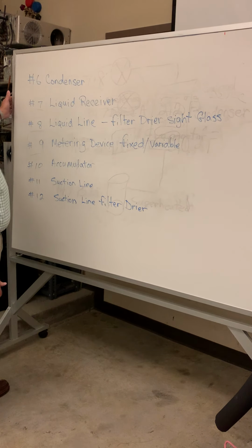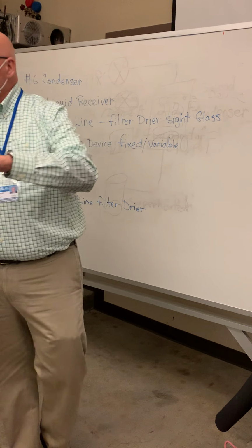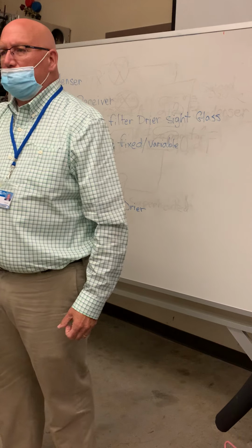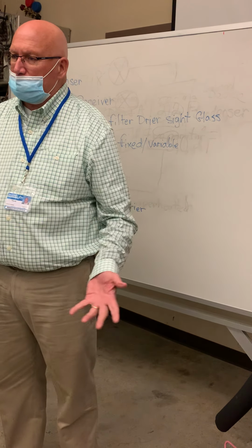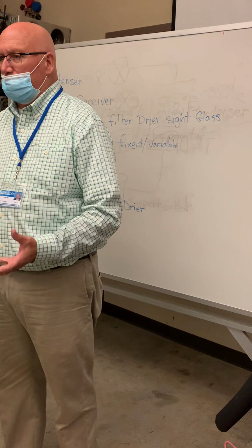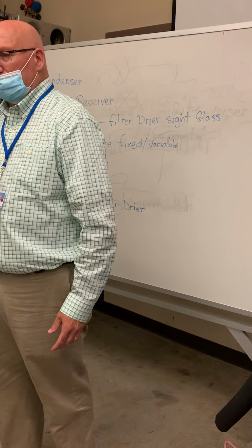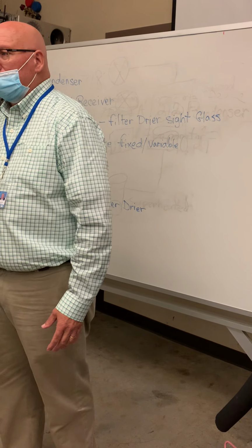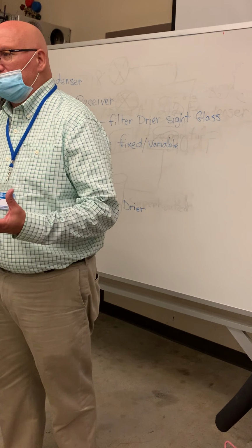What are the other pieces to the system that we're talking about? Well, condensers is one. The condenser, that's the one where I take the sponge and I squeeze it out. That's the one that says it may be 100 degrees outside, but that compressor raised the temperature of this refrigerant to 130 degrees. So that heat wants to leave that refrigerant and go to the outside air that we call the ambient air temperature. That's the job of the condenser.